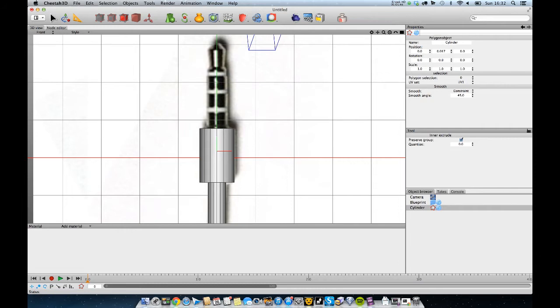Then I'm going to call cover, I'm going to transform, T for transform, or that tool up there. I'm going to pull up. And the same thing's happened again, it's not really the right size, so I'll push Shift X to increase that selection. Go into the scale tool, scale it until it looks about right. I'm going to put it in the middle, and then again I'm going to pull on the scale.